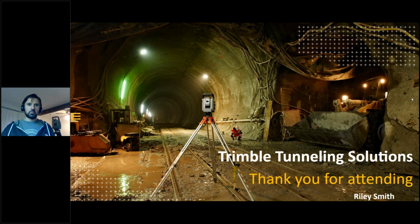There's no specific feature in TBC that's designated breakpoint analysis, but you can do a lot of the network adjustment on data. You can bring all of your traverse, your GNSS, whatever it is you're using for control, into TBC and do the adjustments necessary. One thing that's cool about doing the adjustments in TBC, if any of you doing tunnel surveys are using gyroscopes, you can take that azimuth provided by the gyroscope and put it into TBC network adjustment as an azimuth constraint to improve your tunnel network.